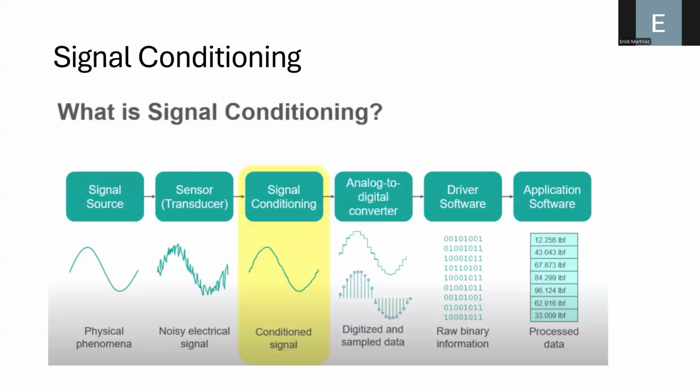Also, this happens a lot with biomedical signals, when you want to measure, for example, the electrocardiogram with an electrical signal, well, that is a mess. You need to place electrodes, but the electrical signal has a very small amplitude, maybe around 20 millivolts. So the signal is relatively small, and you need to amplify that.